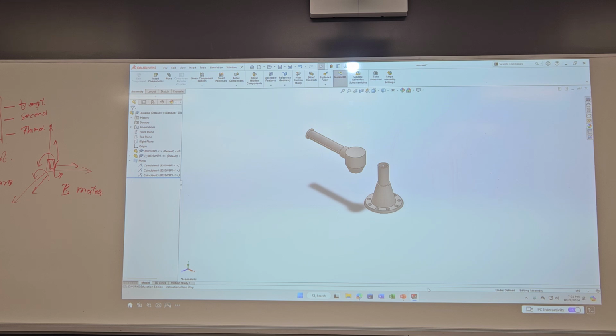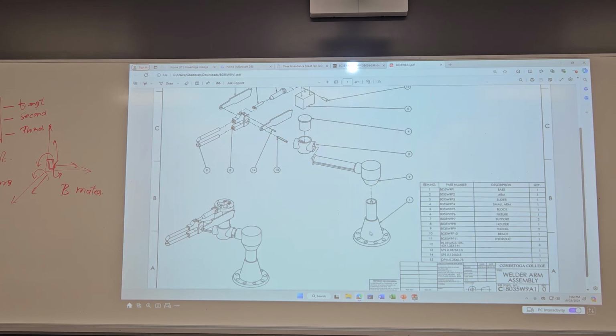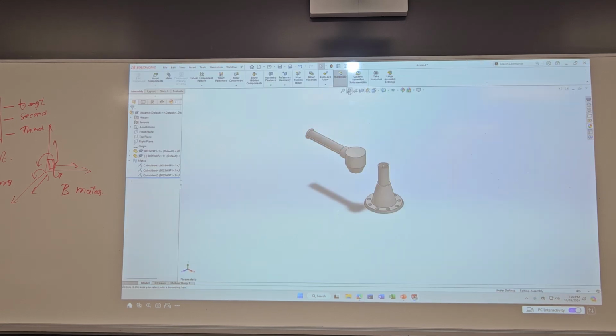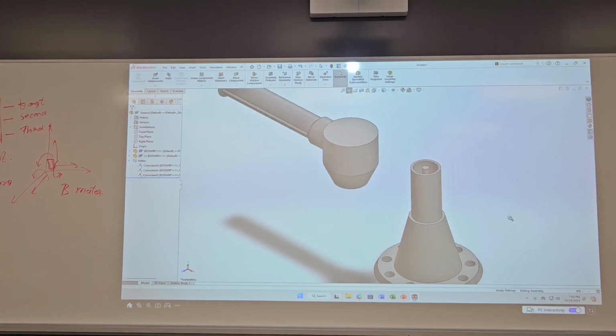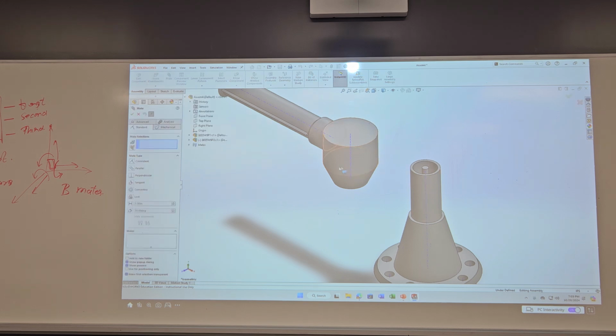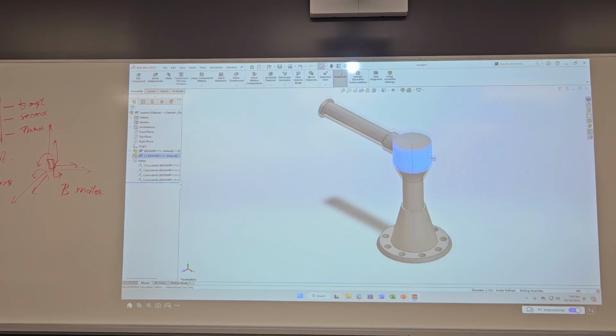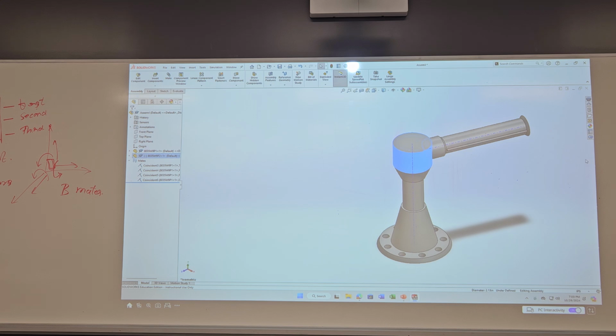Okay, so once the second part comes in, if you look at this, it is axis to axis. So what do you think the best plan is here? Axis to axis. Okay, so visualize axis. I have this axis, I have this axis. Made it axis, axis, coincident. Pretty good. SolidWorks is way smarter than us, I think. It knows what you need. So leave it there. And now it can go up and down, and it can rotate, but it cannot go away from that axis.